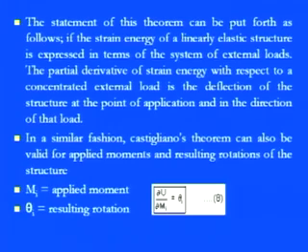Again I am repeating the important statement: the partial derivative of the strain energy with respect to the applied moment always gives you the resulting rotation of the structure at the point where the moment is applied, in the direction of that moment only.